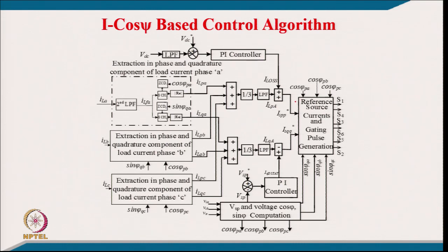So, we get the amplitude of the active current component of the supply current, and here we get, of course, the reactive component of load current. Again for load balancing we divide by 3, and we use a low pass filter to get the amplitude of the quadrature component of the load, and the D-STATCOM has to provide this. Part of this has to be fed locally to the load. So, the remaining comes from the flow into the supply, and multiplying this template with the quadrature here and in phase with this,